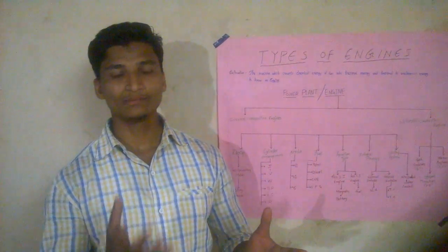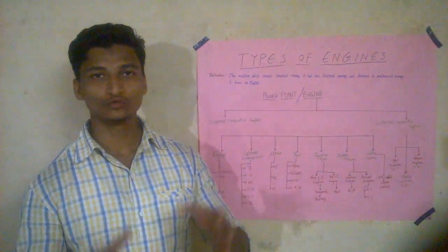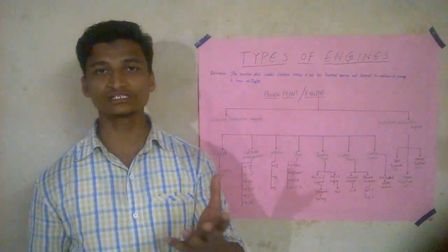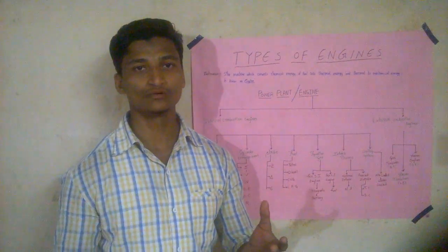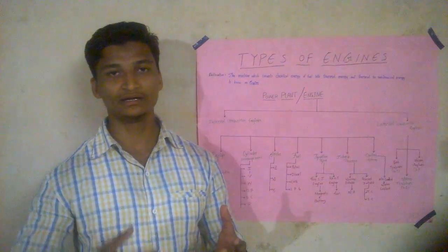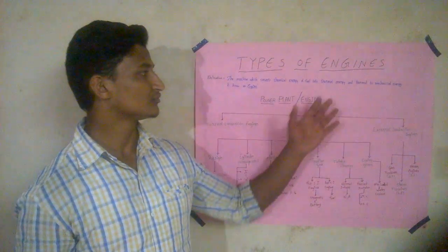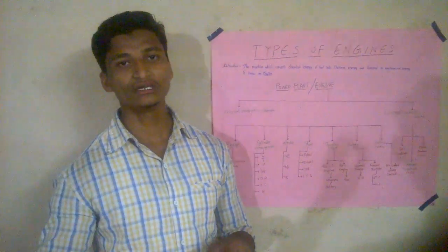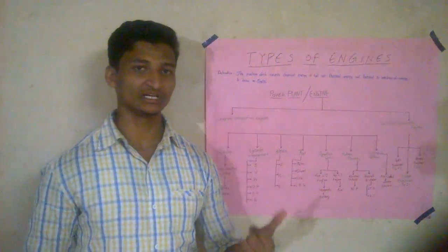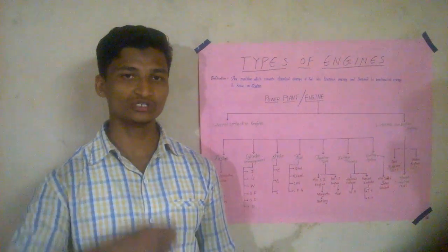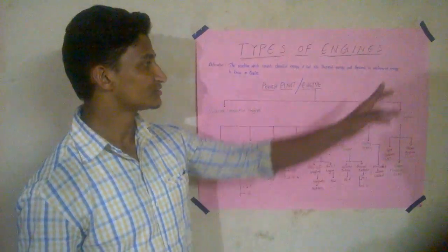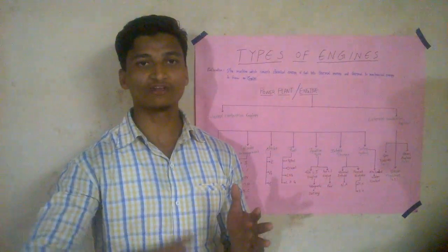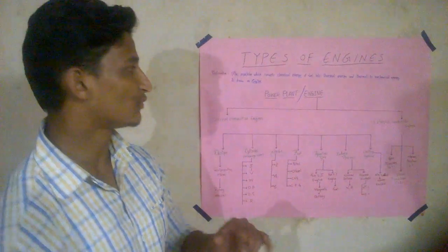The chemical energy is in the fuel which we are using in the cylinder to ignite the charge. It holds some chemical energy, and after ignition, it creates some temperature and raises some heat. That is the thermal energy, and according to the law, P is directly proportional to T. When the temperature increases, pressure increases, and the increased pressure pushes the piston down and rotates the crankshaft. That's the mechanical energy. We get this mechanical energy at the flywheel, at the rear part of the engine.